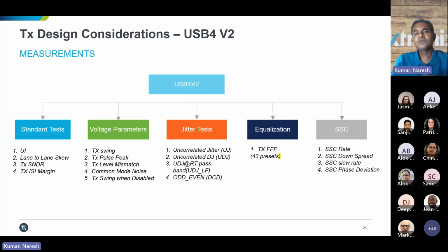Now what we do as a test and measurement vendor, whether it's Tektronix or any other vendor, we make test solutions wherein we combine all these tests into a test suite where the users can make the connections as defined. I'll show you one picture of how the connections for a test would happen, and then run the tests in a sequence, all of them, and generate a report, which will be a compliance test report as defined by the standards body. And that compliance test report is your key to make sure that your design is verified and tested.